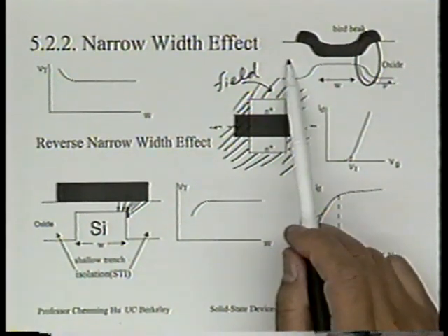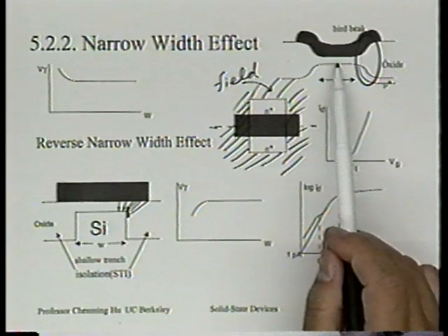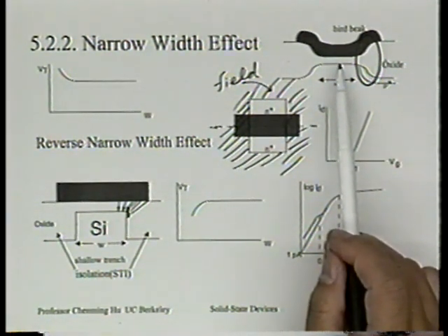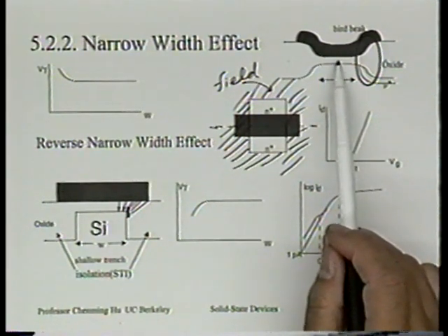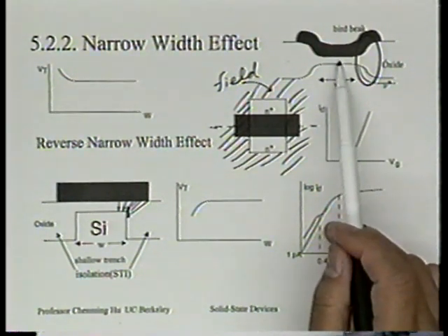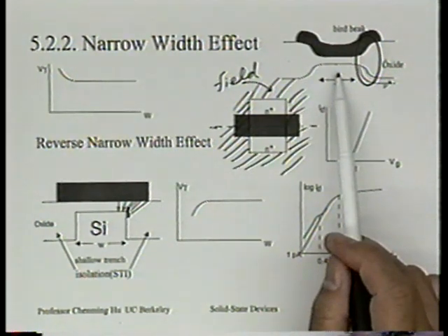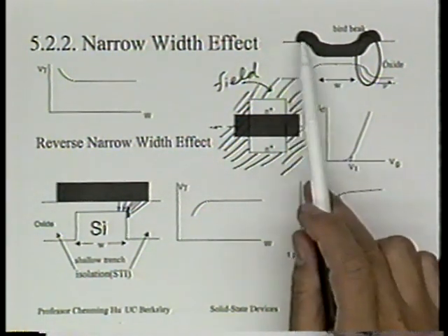Here's the field oxide, and this is the thin oxide, okay? Here we exaggerate the thickness of the thin gate oxide. You know, this is that 100 angstrom, or 20 angstrom, or 12 angstrom oxide we just talked about a while ago, all right? That's what this oxide is, very thin gate oxide. Underneath is the channel region, all right? On top is the polysilicon gate.